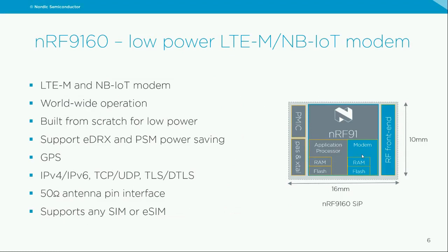We also ensure that we support all the power saving modes as they are defined in the 3GPP standards. So even though 81-second eDRX timing is a common benchmark out there, perhaps for the reason that some chipsets don't support much more than that, our device supports all defined sleep periods for eDRX and PSM as they are defined by 3GPP.